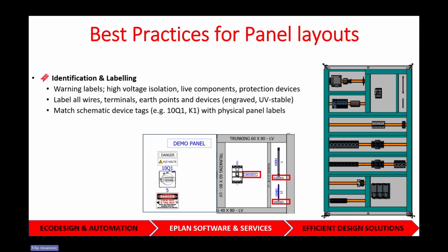You also want the device tags in your panel layout to match what's in the schematic. Now with Eplan, it's really easy to do this because you're dragging existing components onto the panel layout, so it shouldn't be a problem, but definitely something that you do need to keep in mind.